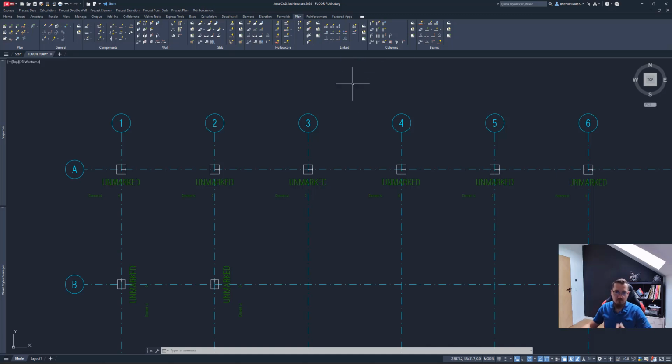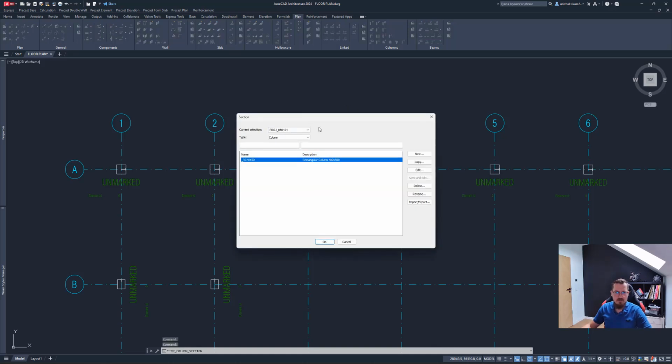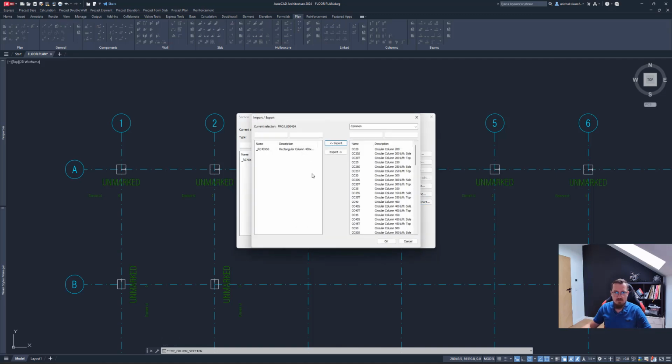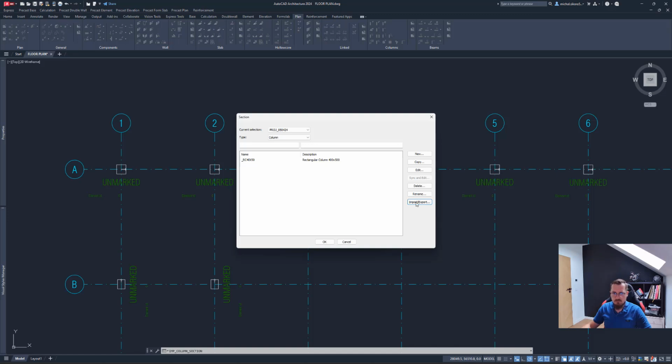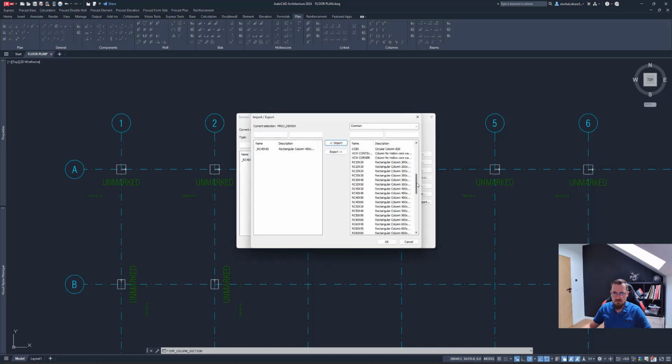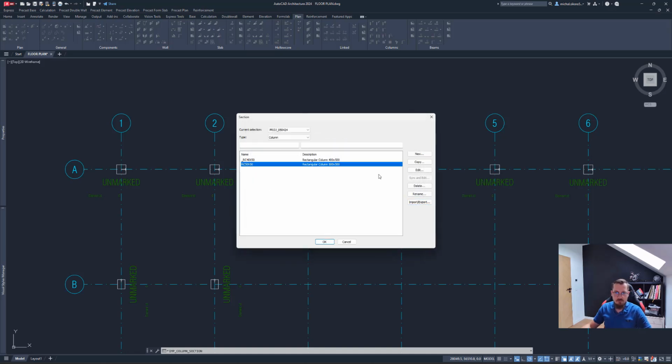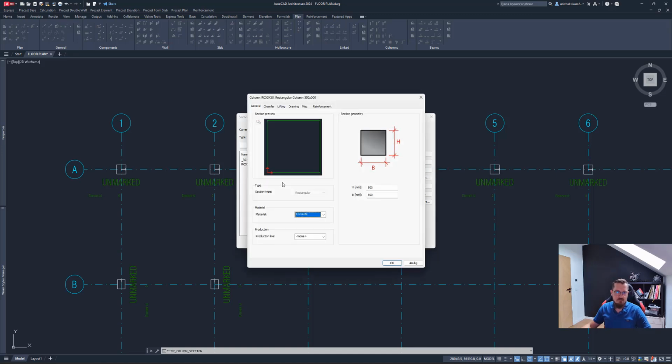But in order to modify the rebar template for the columns, we actually have to go to the definition of the columns. I have one definition in the project itself. Let me import the definition of the columns as well, the 50 by 50. Oops, I didn't import that. You always need to import and accept that. So we have our column here, and let me edit that.